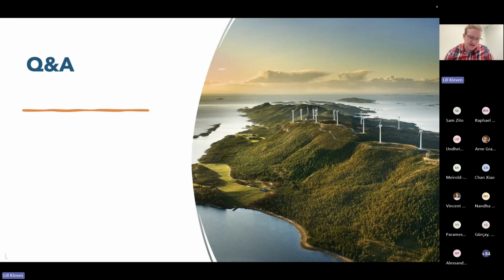try it out. But what we want with the new European Wind Atlas is that it be used in conjunction with this scaling approach, which is more suitable for the new European Wind Atlas data because it's limited. It's only up to 500 meters and it doesn't include pressure gradient information, for example, which is pretty necessary. But if you want to try it, in WindSim 12, there is an experimental feature. You reach out to me via support and I can give you further details.